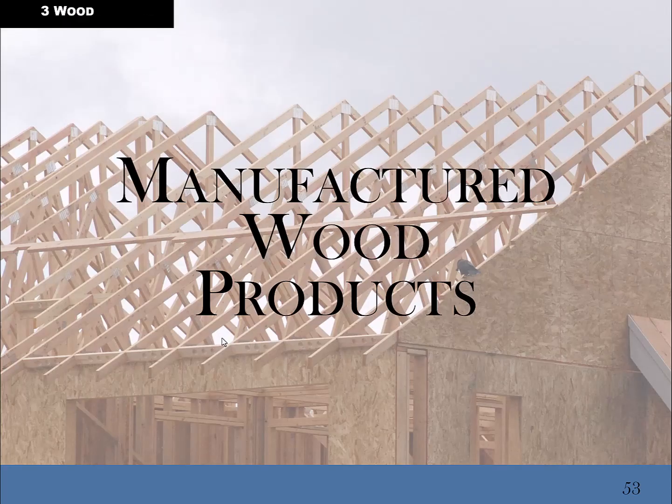Manufactured products, there are other products here that I hadn't mentioned, so there's just a brief mention here about trusses. When you look at this roof, a traditional rafter roof where you've cut two rafter boards to lean them up against a ridge board, you get a very different look here. When you look at this picture here, there's no ridge board. So when you have a roof with trusses, that's the first giveaway that these are truly trusses, because there is no ridge board. Whereas when you have rafters, you've always got to have them lean up and sandwiched together on a ridge board at the peak of the roof.